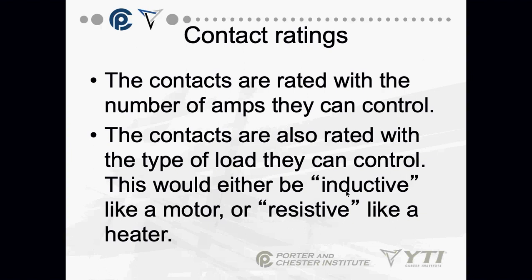But it's very important on the contacts. You can't put a contact rated at 5 amps on a compressor that you know under running conditions will pull 60 amps. You can't do that. It's going to melt the contacts down.